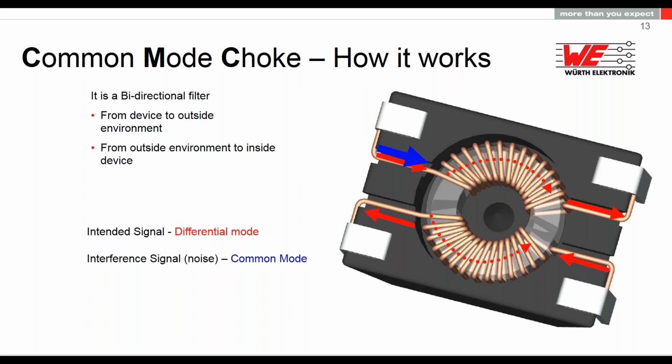Now, let me make again the right hand rule. Right hand rule, the magnetic field goes inside, the same as with the differential, the current goes through it, but on the minus pole we have again a common mode current in the same direction, with the same right hand rule. Now, what will happen here? If you apply that, you decide, oh, now we have a turn. Now we have exactly the same direction of the magnetic field in both windings, and now this magnetic field is transferred into heat. This is how a common mode choke works.